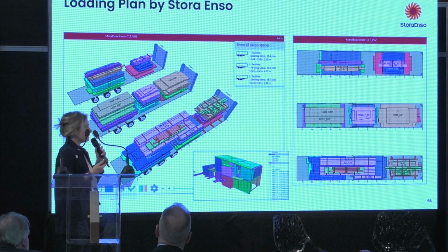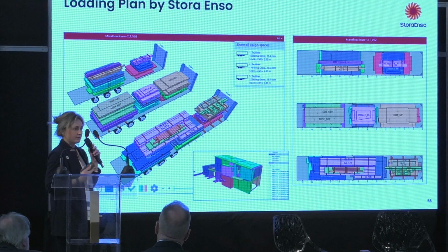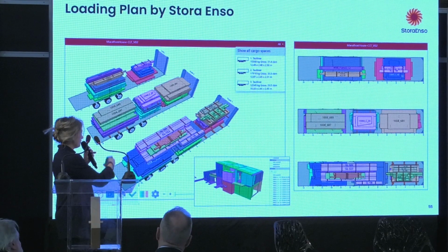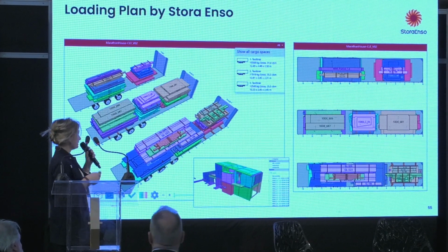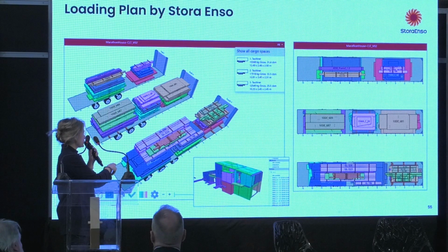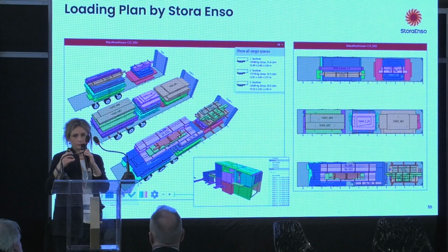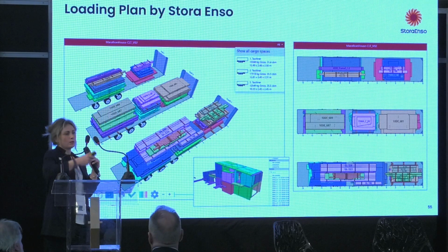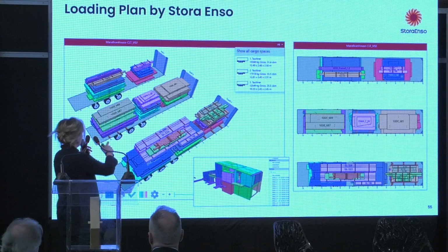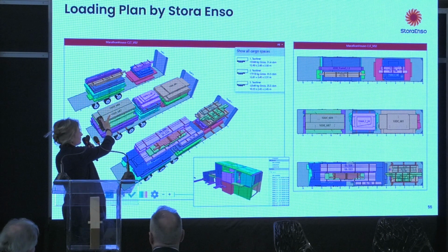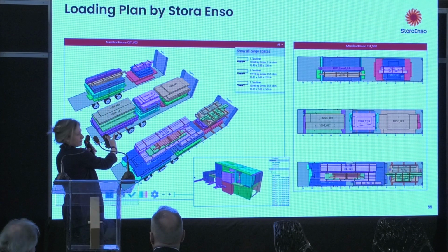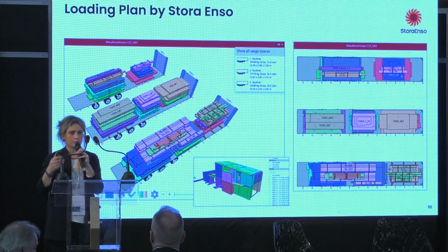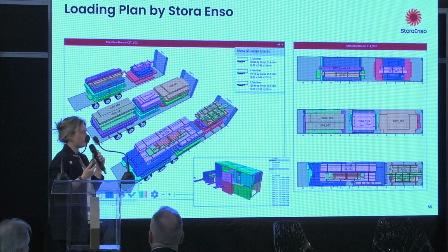So you already know how many trucks arrive in the construction site, how the panels are put together into the truck, and the best is that each element is put on the truck exactly in the same order as you need to install it. So it means that this panel, for example, should be installed before this one. So it's completely following the order that you need in the construction site, allowing you to save a lot of time.